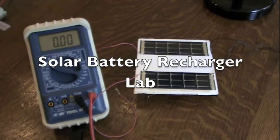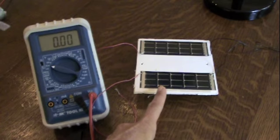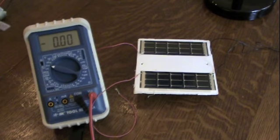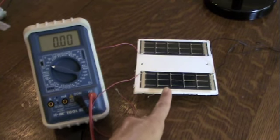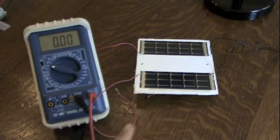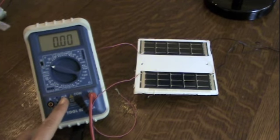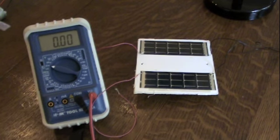In this lab, we build a battery recharger unit using 2 solar cells and 2 nickel metal hydride rechargeable batteries. Before we get into how this unit is constructed, what I want to do first is test each solar cell to ensure I'm getting the voltage and current I expect. Now, the manufacturer of the solar cell rates these cells at 3 volts and 37 milliamps. So I'm going to use my multimeter to test the voltage and the current to see if that's what I'm getting out of each solar cell.